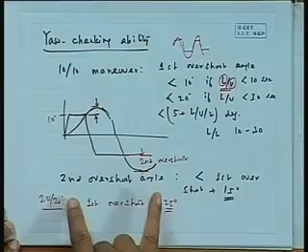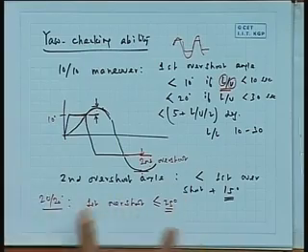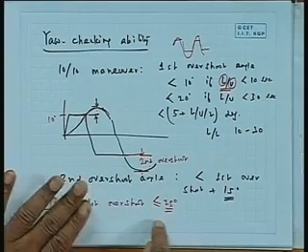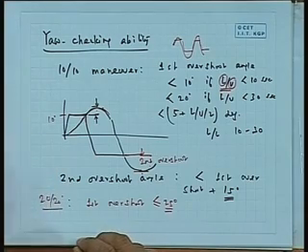Now just to quickly say, because we have to end very soon, for the 20-20 zigzag maneuver, another criterion is there, where the stipulation is only that the first overshoot should not exceed 25 degrees. Essentially, this is limiting the ship's ability to turn in the zigzag maneuver.